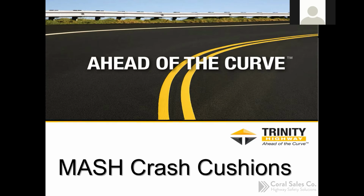The QuadGuard, which we'll mainly focus on today, was actually developed in 1995, right about the same time that the NCHRP 350 crash standard was developed and introduced. So that was the most recent crash standard before this MASH compliance standard. MASH stands for the Manual for Assessing Safety Hardware. And again, it is a very long book of very detailed requirements for testing all the various roadside hardware products that you see out there.